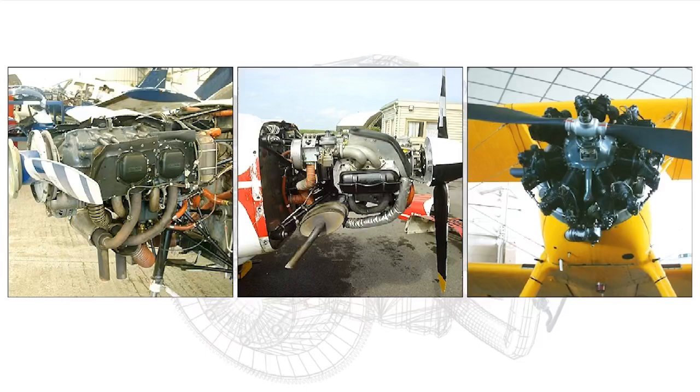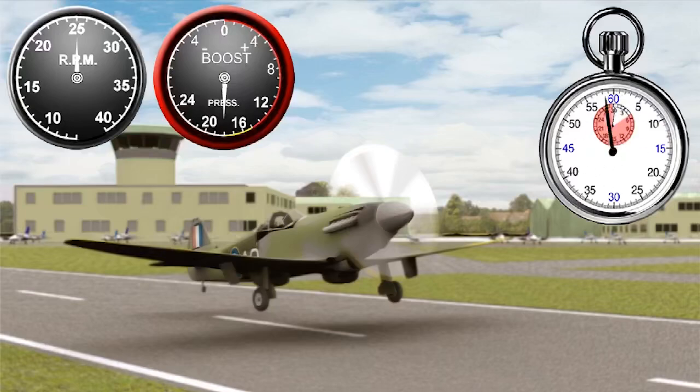The power output of each engine is specified by the manufacturer. Having said that, however, each manufacturer also gives various power outputs which may either be obtained at specific engine control settings or used for limited periods of time. Takeoff power is the maximum power the engine can develop. Its use is normally time-limited.